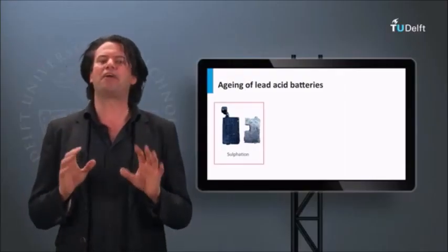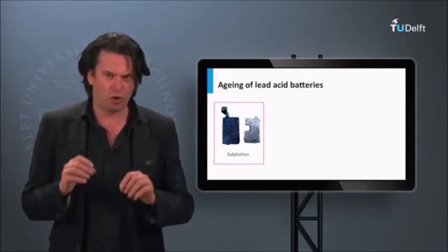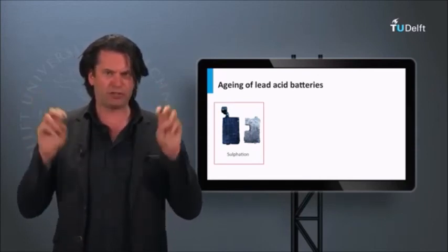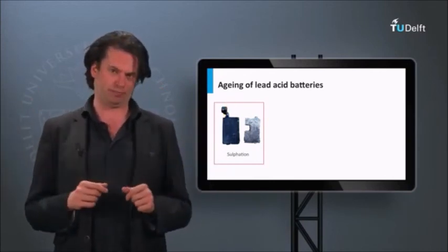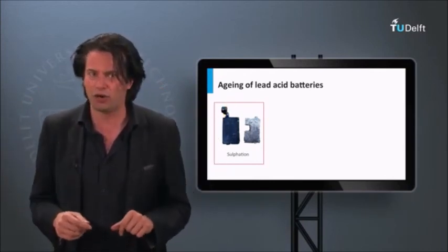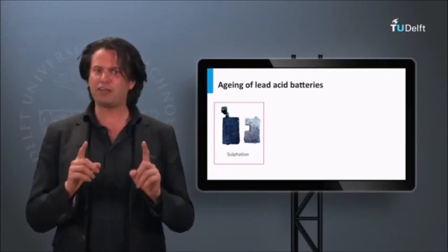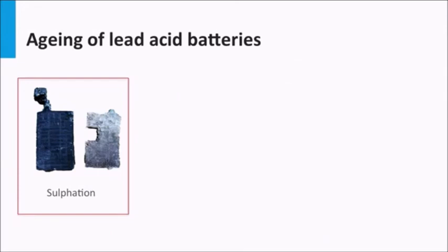When we say that the battery has a limited cycle life, or that it has permanently run out of use, what exactly happens to it? What exactly is this aging effect on the lead-acid battery? Let us briefly discuss this. Sulfation is one of the major causes of aging. Insufficient recharge after discharges causes sulfate crystals to grow, which cannot be completely transformed back into lead or lead oxide. Thus the battery slowly loses its active material mass and therefore its discharge capacity.